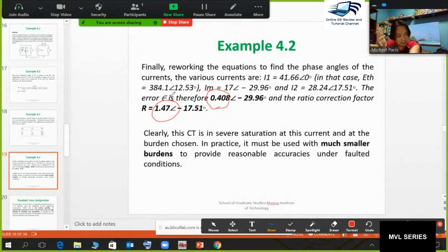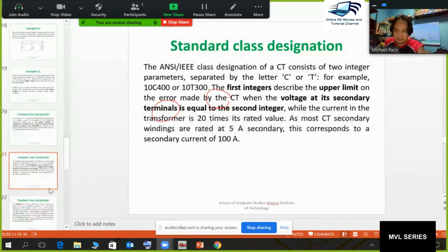So lower the resistance value in order to get the turns effective ratio in a much more accurate value. So that's the moral lesson of that: design your current transformer ratio with a lower burden impedance.